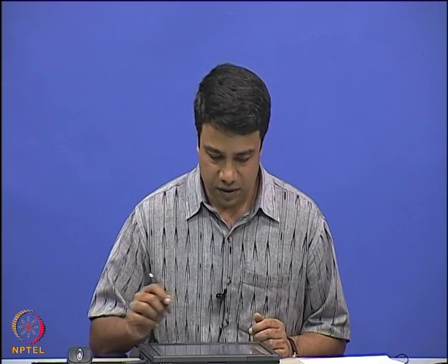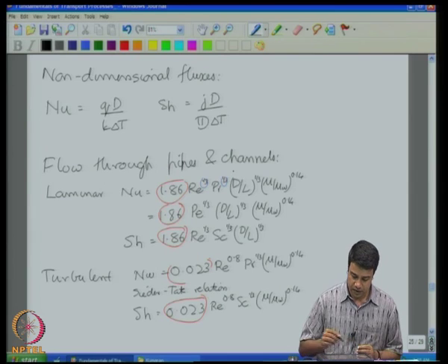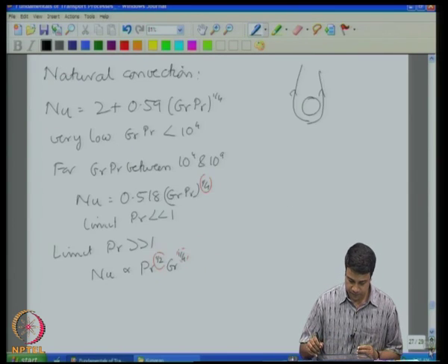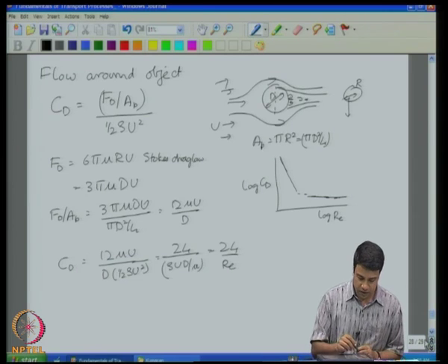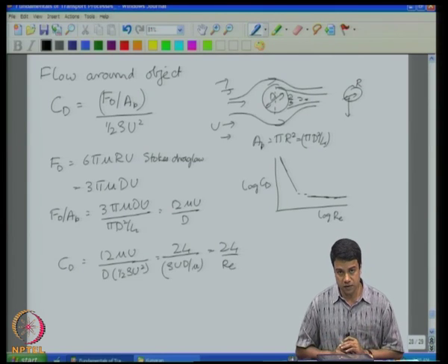Now, in the remaining course, I have told you what can be done so far with dimensional analysis. In the remaining course, we are going to try and give some motivation for why these kinds of things come up. So, for example, for the drag force in the flow around a sphere, I know that the drag force just from dimensional analysis has got to be equal to mu r u times some constant. I do not know what that constant is.